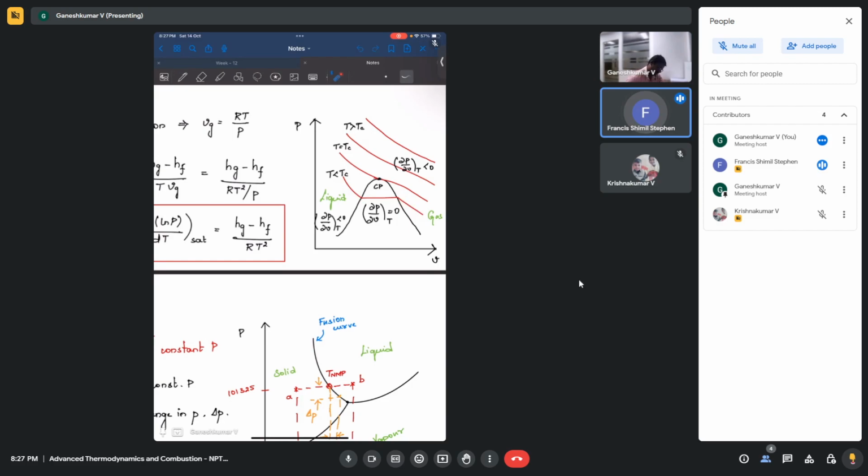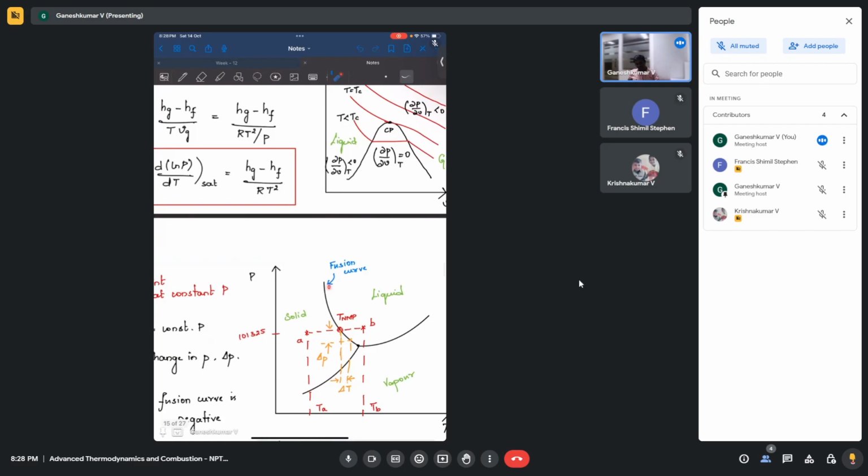Yes, sir. In the phase change region, only volume expansion takes place, right? In the phase change region, this is the mixture region, so both pressure and temperature remain constant during this dome. That is the reason you should represent this with one point, which is Psat and Tsat, and that is what is lying in this line.